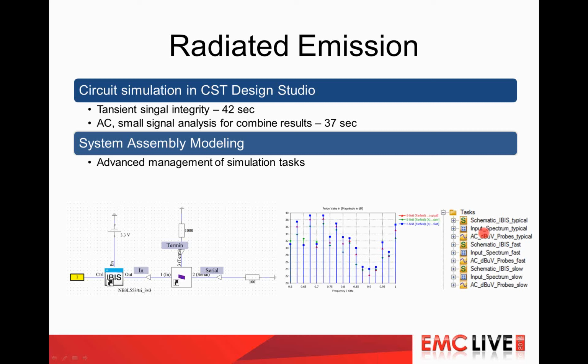And you can see here that I can place this on the circuit schematic. CST Design Studio is not just a pure circuit, it also offers functionality for the management of simulation tasks. So I could place all the different tasks basically as a kind of job queue into Design Studio, and run them all in an automated fashion. This is important because what we could do now is maybe move the trace around on the 3D and rerun the 3D model, and right away also get the results from all these tasks with just one push button, which makes the management of tasks and the definition of more complex simulation projects very, very convenient.